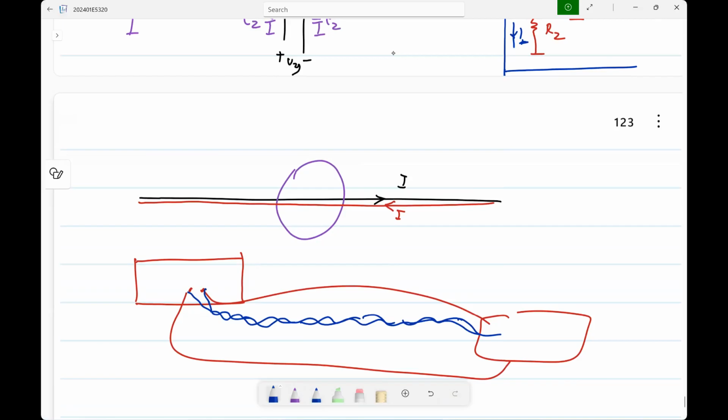What is Kirchhoff's voltage law? Will it add up to zero? What does it actually add up to? Where does it come from? What are the fundamental equations from which you derive all this? What's the fundamental set of equations from which you derive Maxwell's equations? Going around the loop, it is equal to something. What is it? There is a rate of change of magnetic field.